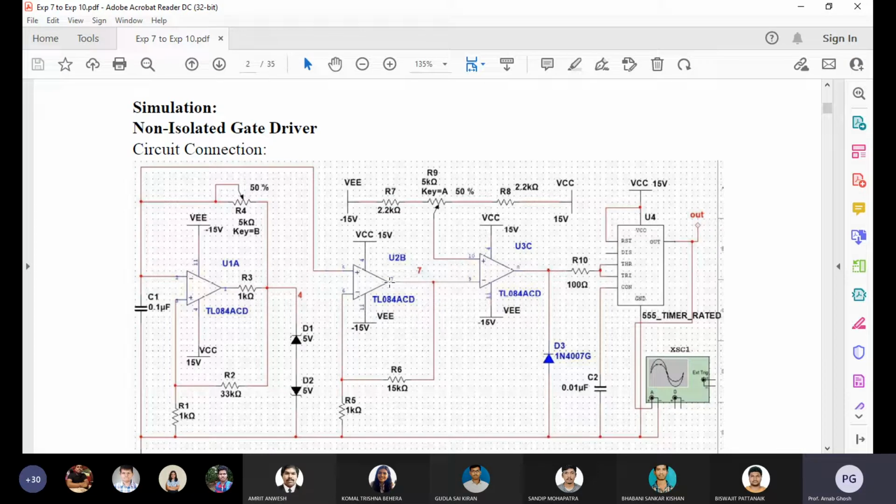If the height of that waveform has been increased, you will get that triangular waveform with more amplitude from this first oscillator, the first op amp. So the purpose of the first op amp is generating the triangular waveform. The purpose of the second op amp: you can see the terminals connecting 5, 6 and 7. VCC are common for all the cases.